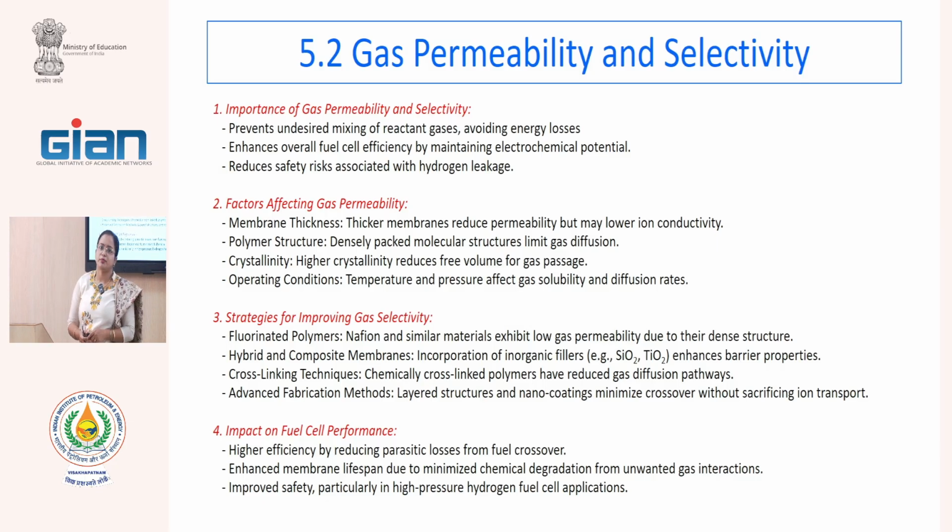Okay. So, while we are choosing different membrane materials, water management is an issue, an operational activity we should be maintaining. But also, while choosing particularly which membrane you are going to use, an important factor is permeability and selectivity. I also told in the last class that they are counteractive. If you have more permeability, selectivity goes down. So, they have to have a balance between them.